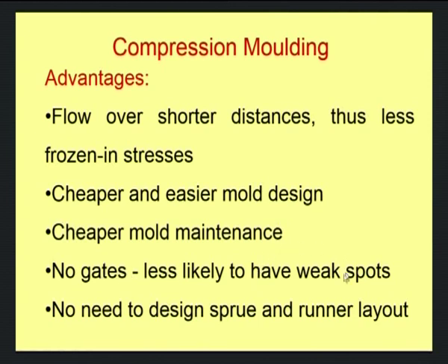So, therefore, this will also result in weak spots. Weak spots are nothing but the improperly cured part of the product that occurs when a resin has to flow for a large distance before it fills the mold. And then, no need to design a sprue and runner layout.